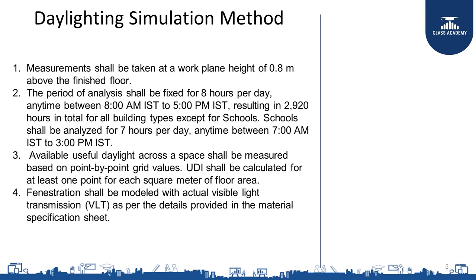Now let us look at the method. Measurements shall be taken at a work plane height of 0.8 meter above the finished floor. The period of analysis shall be fixed for 8 hours per day. These 8 hours can be any time between 8 AM IST and 5 PM IST. This will result in 2,920 hours in total for all building types except schools.